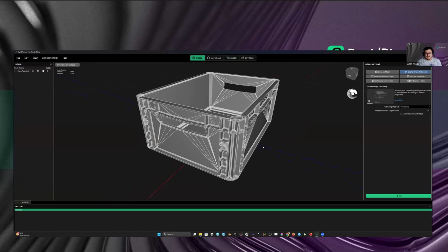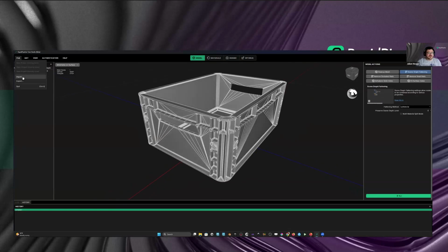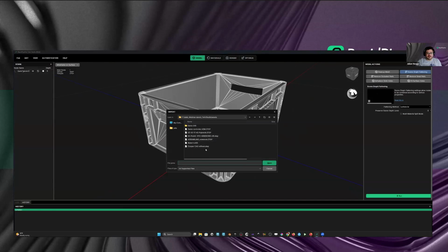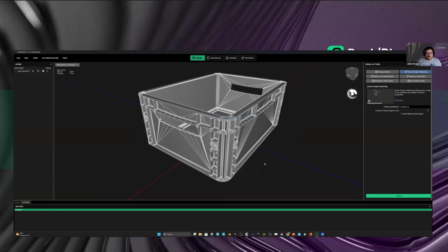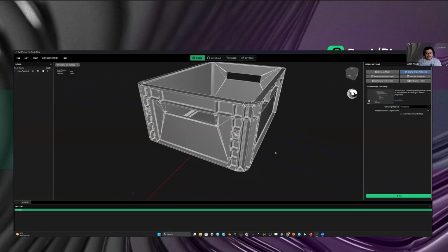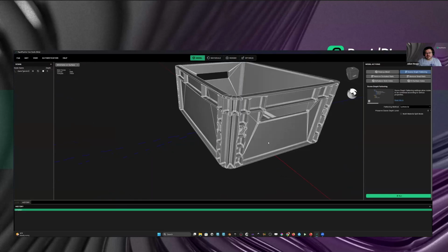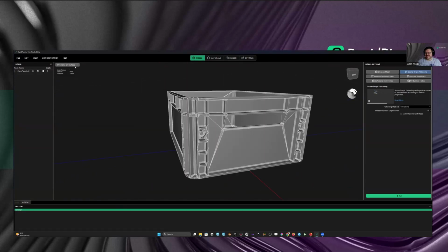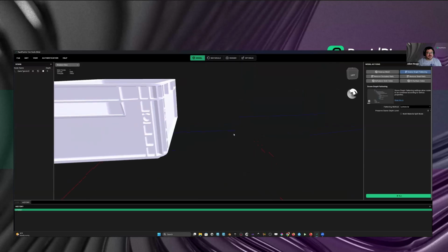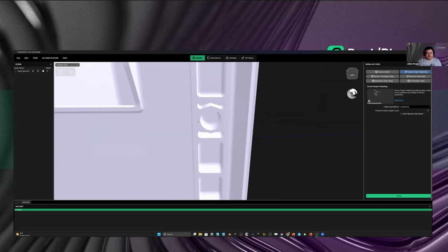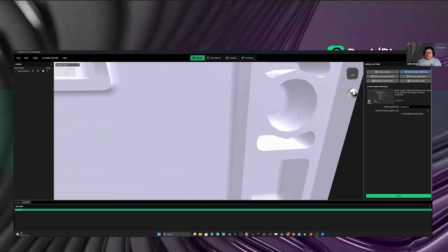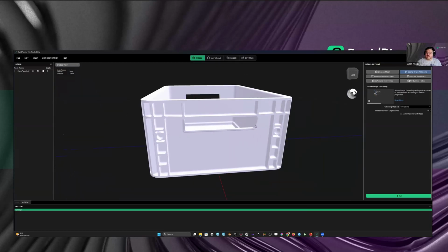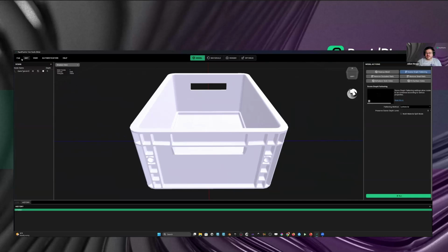And basically this was now in a custom resolution. So if I'm going to the import tab again, just to demonstrate it, I'm going on the same box asset, open, and now I will just do the extra coarse preset just to see what changes. And it should definitely reduce the resolution by a lot. So as you can see here, it's still the box, you can still see it, but especially if you go in the shaded view, for example, and you look at the shape of the boreholes here, this is not necessarily a resolution you ever want for your visualization. But the import was pretty quick and easy. So that's a benefit here.